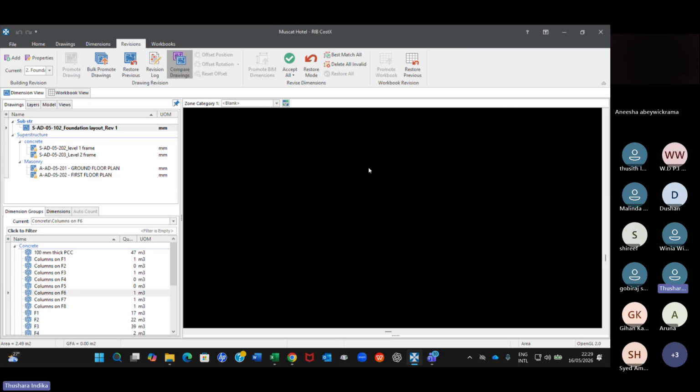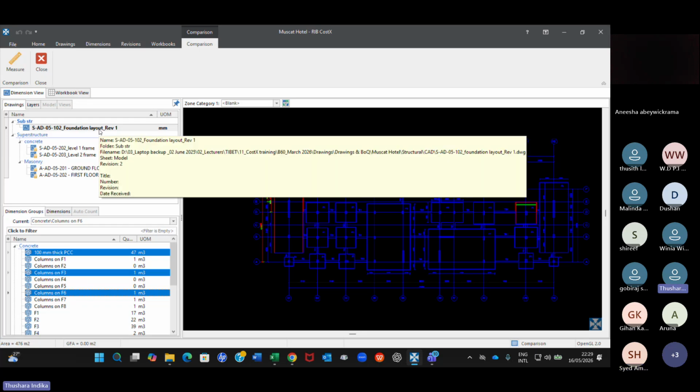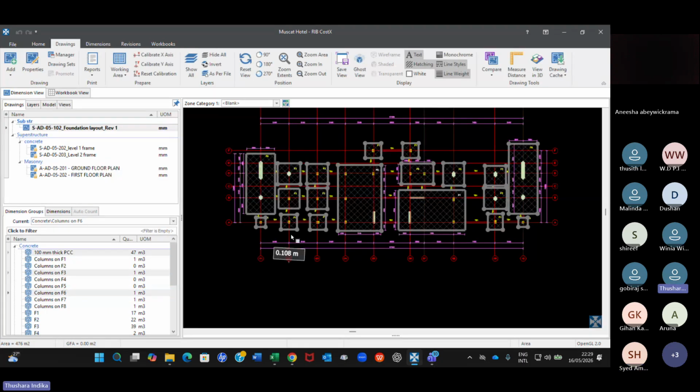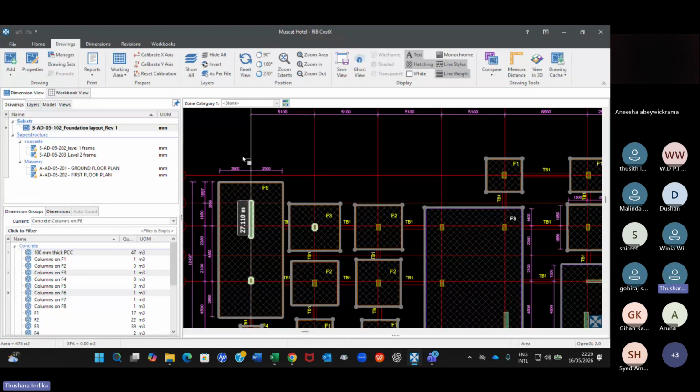Mesh lines, okay. Right. And then what you need to do is you have to select the affected dimension groups, PCC, F3 and F6. You select, and then you select the division 1 row. Click on that. And you will see this. And then you have to drag the line to the new position here.